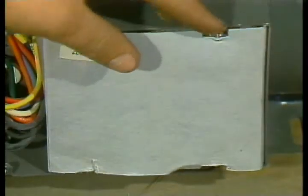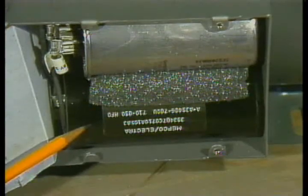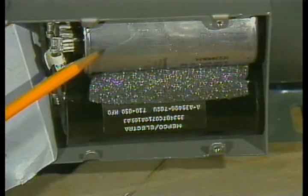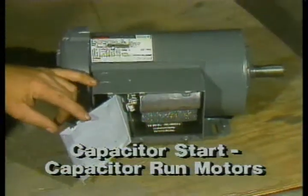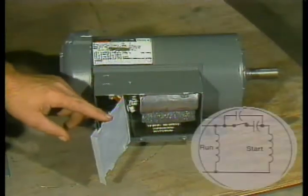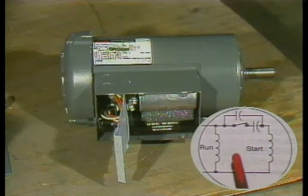Still other single-phase motors use both an electrolytic and an oil-filled capacitor. These heavy-duty motors are usually called cap-start, cap-run motors. The capacitors are connected in parallel while the motor is starting up. A centrifugal switch cuts out the electrolytic start capacitor during run.